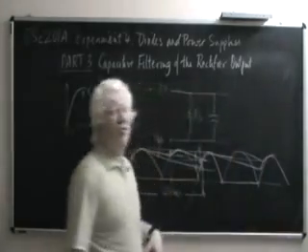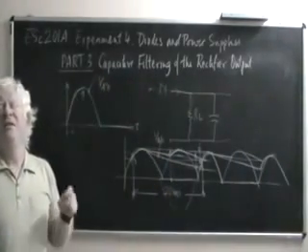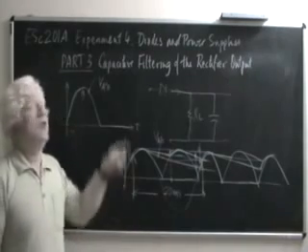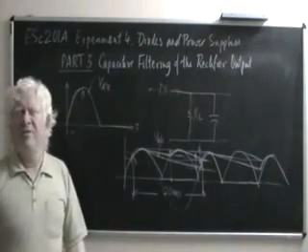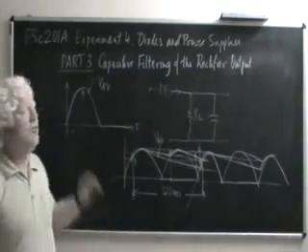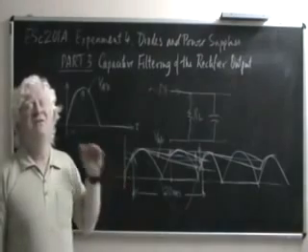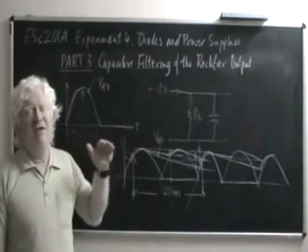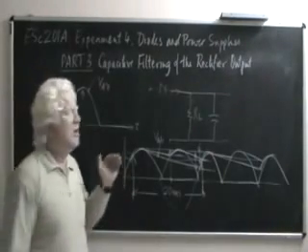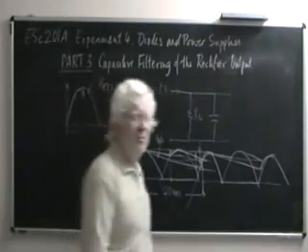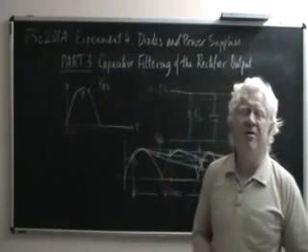A far more level waveform than what you would get with the same capacitor, same resistor if you had a half wave rectifier. A full wave rectifier is giving you a far more constant output, an output with much less time variation. So clearly a full wave rectifier scores over a half wave rectifier in this respect, and that's why we use a full wave rectifier.